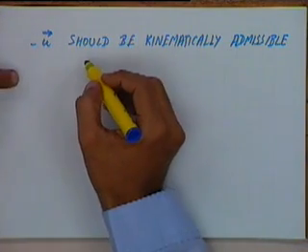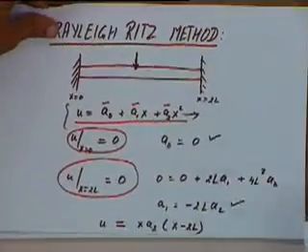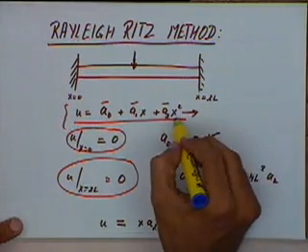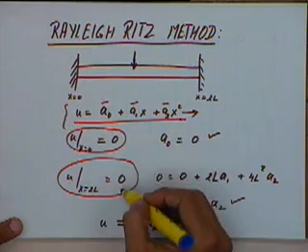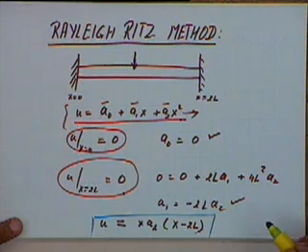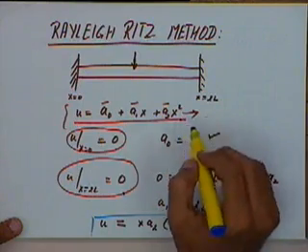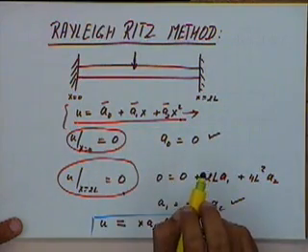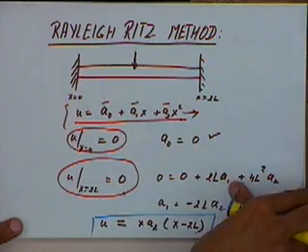Okay, that means whatever the boundary conditions be, those conditions should be met. For instance, in this example, we took this to be the initial field, and then we said that these are the boundary conditions. We applied these boundary conditions, and this field reduced to this expression. So we made an initial assumption about the field, and then ensured that the boundary conditions are met. Or we made sure that this deformation is kinematically admissible, right, kinematically permissible.